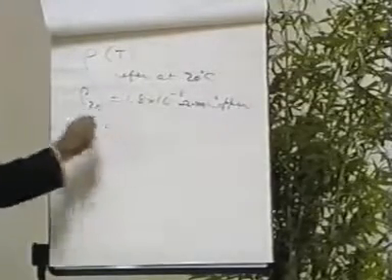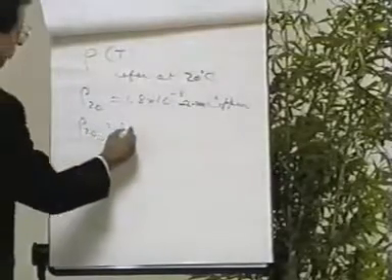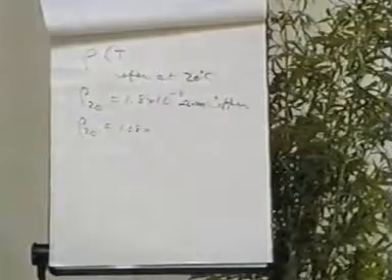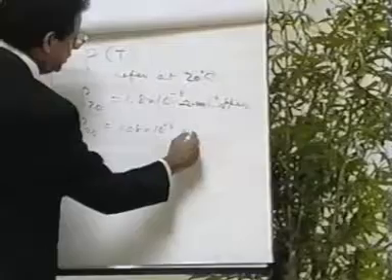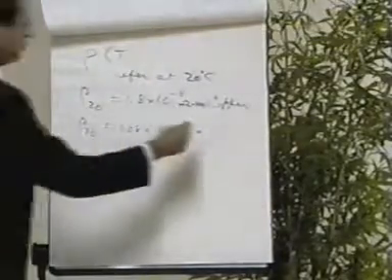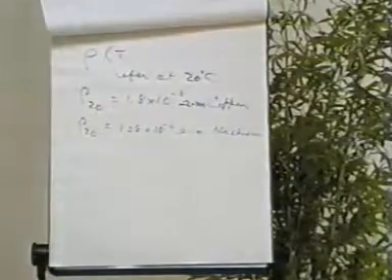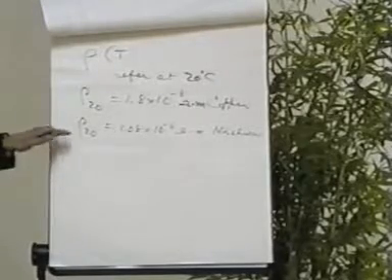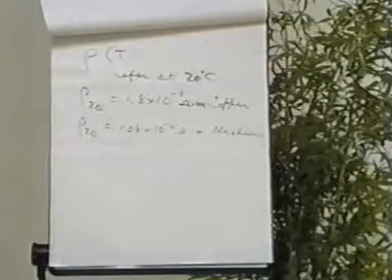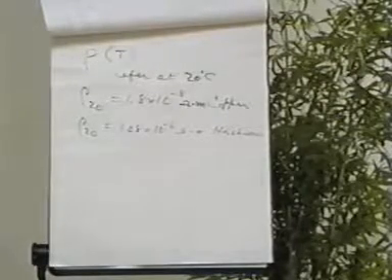On the other hand, if you take some material like nichrome, for instance, you find the resistivity there is 1.08 times 10 to the minus 6 ohm-meters. This is for nichrome. And you can see quite an interesting contrast by 2 orders of magnitude, that the resistance is much, much higher for nichrome than it is for copper. Copper is notorious for a very low resistance. That's why it's used so frequently in conductors.